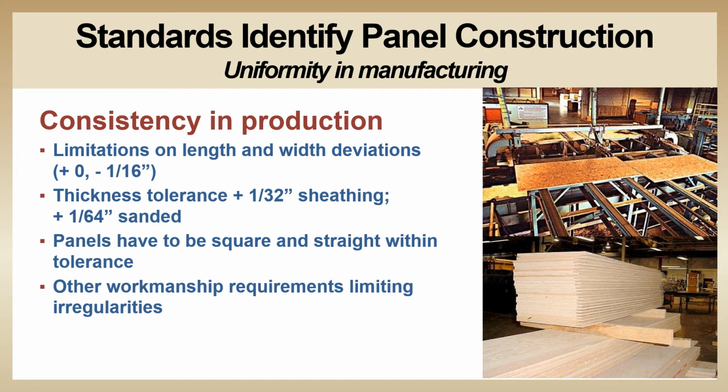The construction of wood structural panels is defined in the standards and therefore provides the users with panel performance that is both consistent and reliable. There are limited deviations in all dimensions, including the width, length, and thickness. The panel must be relatively square with straight, uniform edges. There are other workmanship requirements, including the quality of the repairs to the veneers, the types of fillers that can be used, and many others. Again, standards provide you with a known quality of product.